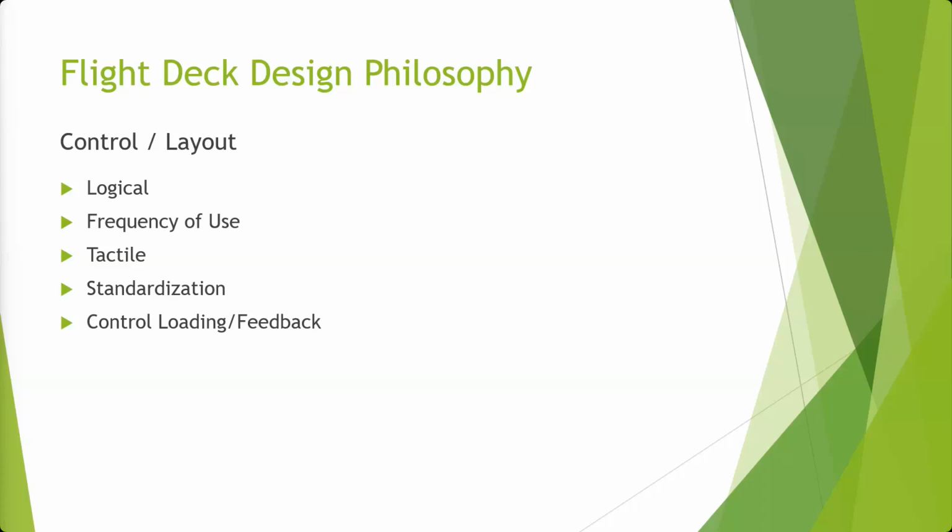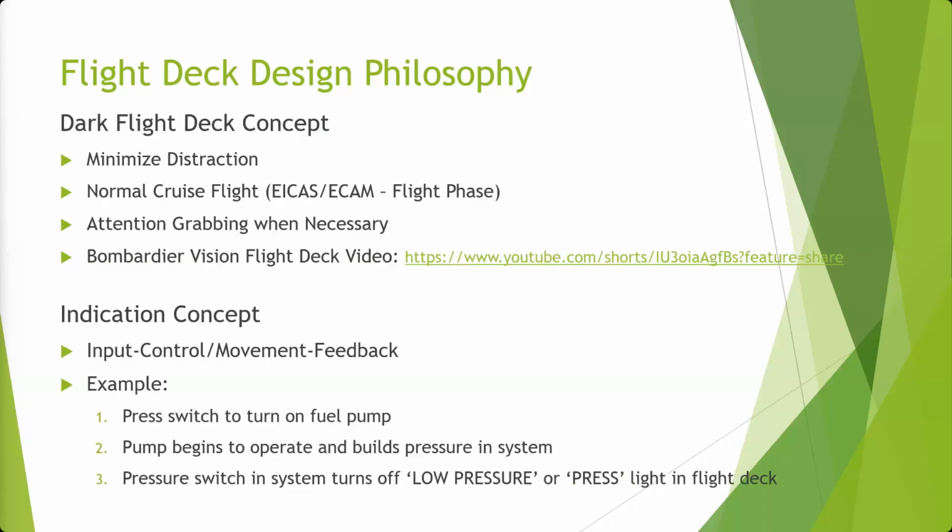The next part of flight deck design philosophy, another very important one, is what's called the dark flight deck concept. I talked with a couple groups yesterday when they were in the sim about this. Not everyone asked, but there was some question about that. The key point of the dark flight deck concept is that we want to minimize distractions. By minimizing distractions, we can draw attention to an abnormal or non-normal situation when one occurs, and it doesn't get lost in a sea of other things going on.